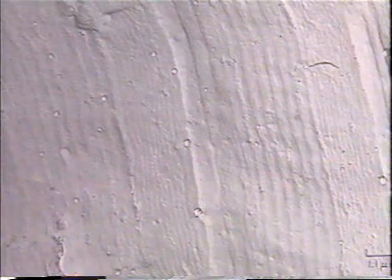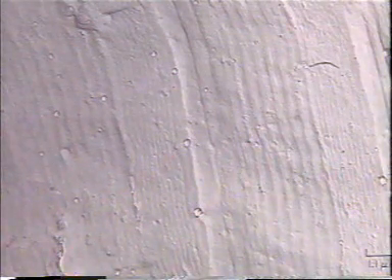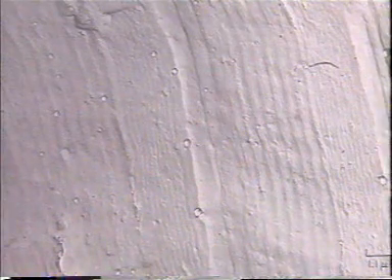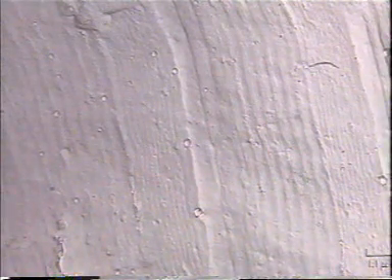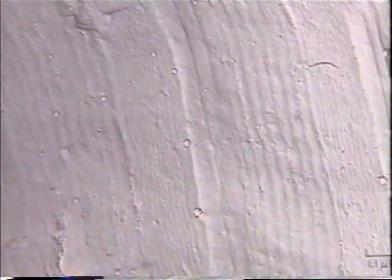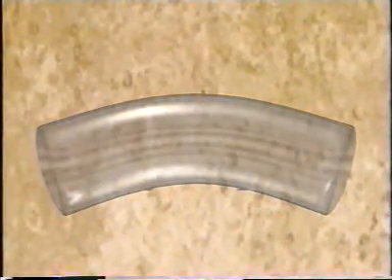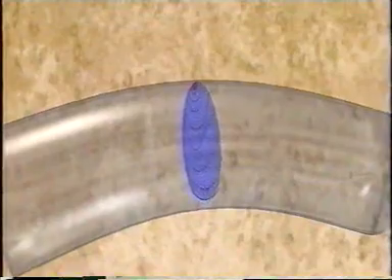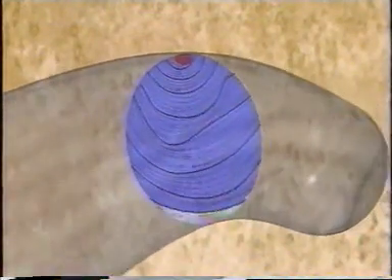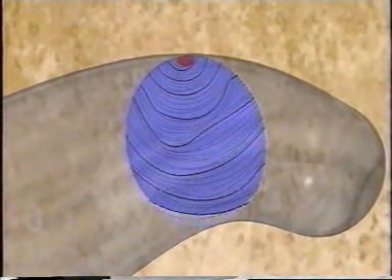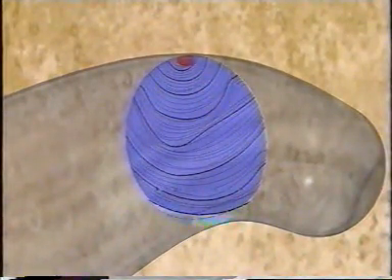Two sets of striations can be seen. The widely spaced striations are caused by a higher stress. The more closely spaced are caused by lower stress. The striations never cross. They are generally concentric or parallel to each other. Each striation marks the tip of the crack at some point in time during the test or service life of